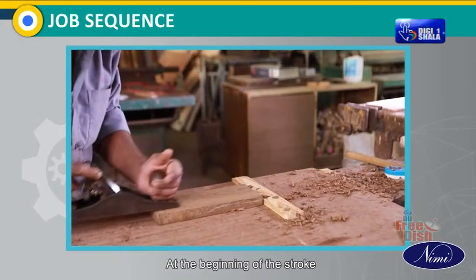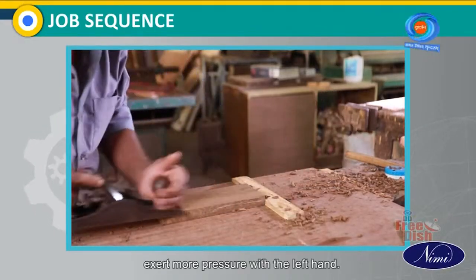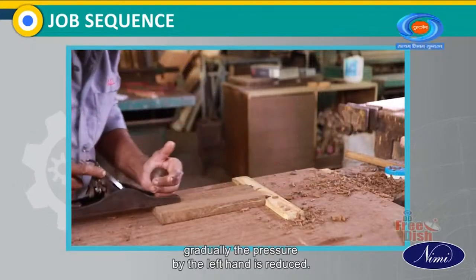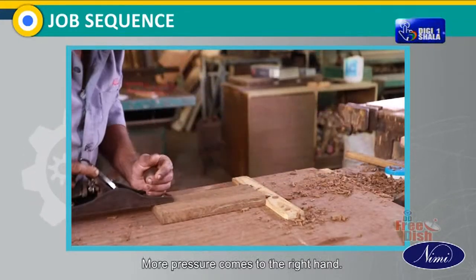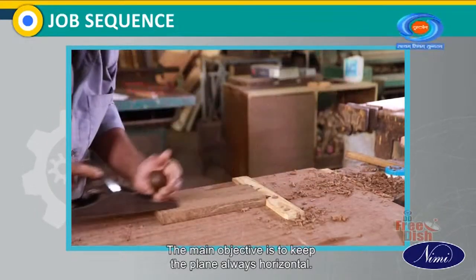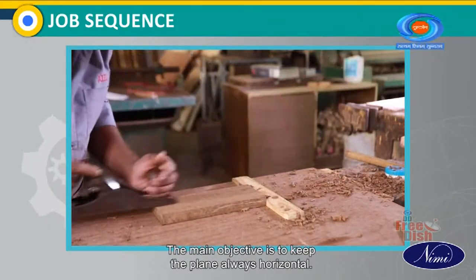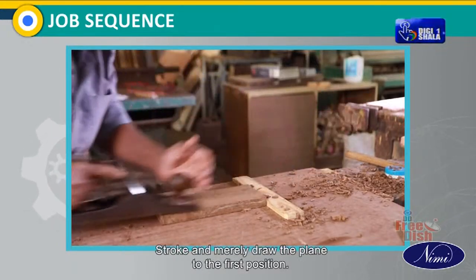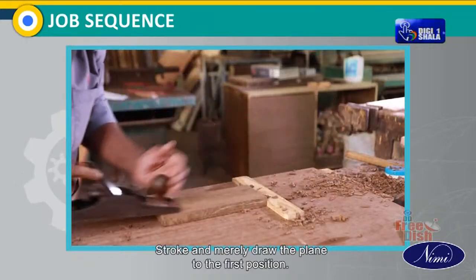At the beginning of the stroke, exert more pressure with the left hand. As the stroke proceeds, gradually the pressure by the left hand is reduced. More pressure comes to the right hand. The main objective is to keep the plane always horizontal. Release the pressure on the back stroke and merely draw the plane to the first position.